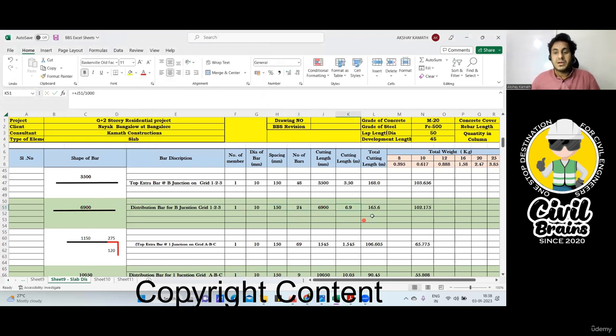Cutting length is 6,900. In meter it is 6.9. Total cutting length will be 6.9 into 24 into 1. That's it. And the weight of the 10 diameter bar, how much will it be? 165.6 multiplied by 0.617. This will give me the total weight.